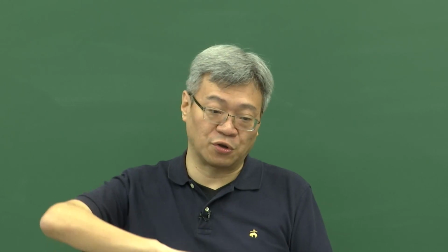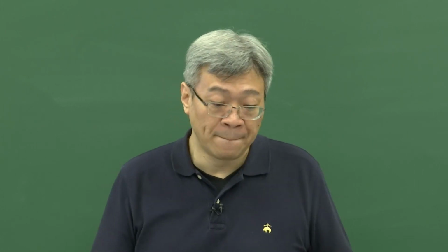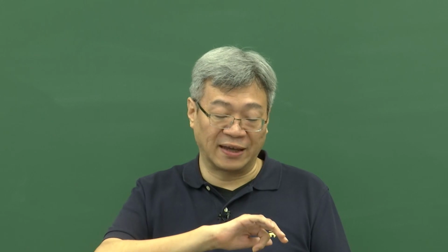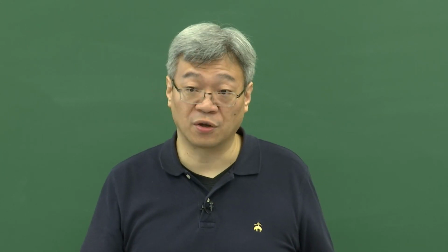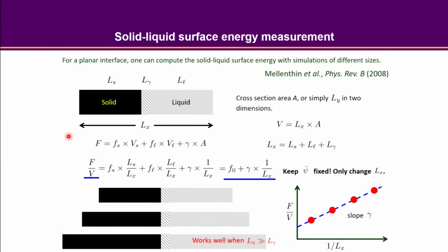So for different mixed orientation, you are expecting that the dislocation structure on the surface is going to change, right? That would give rise to a different grain boundary energy contribution. Then you can make a plot of gamma GB versus the mixed orientation. And for the really low angle, you are expected to rediscover this Read-Shockley relation, right? But in order to have all that information, you will need to know how to determine even the grain boundary energy from simulation. So think about this logic and see whether that applies also to the grain boundary case.